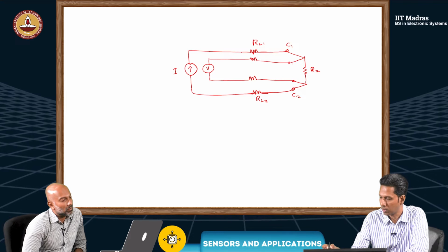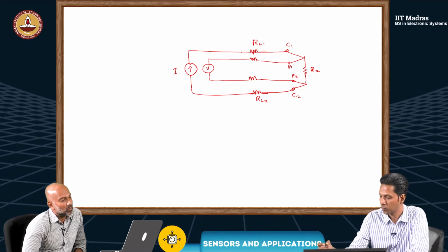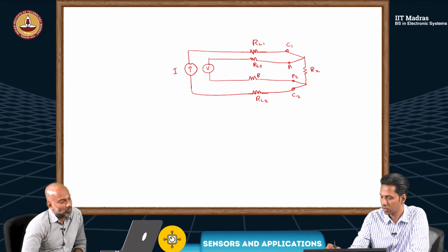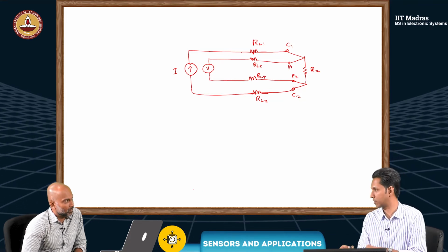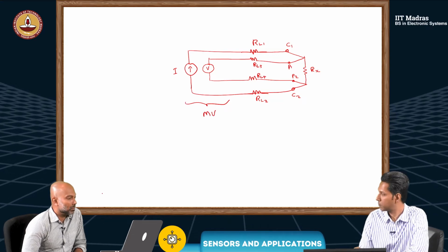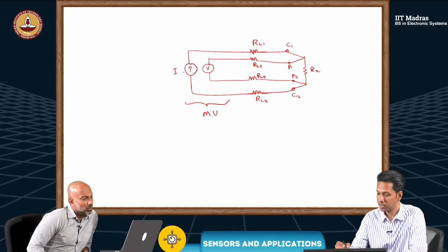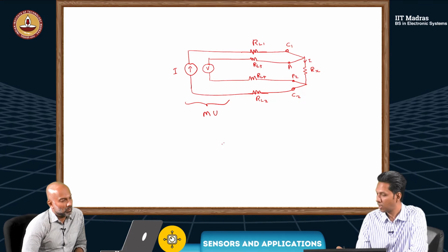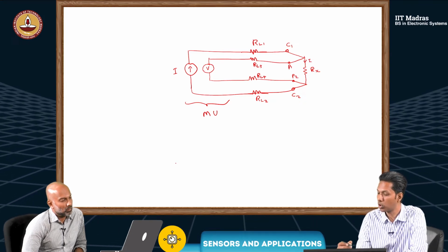And this terminal, let's say this is P1 and P2. And this has got RL3 and RL4. So these RLs represent the lead wire resistance. This region is my measurement node. So what we said is, let's say this current I is flowing through this, and then it has got I into Rx voltage there. I measure it using a voltmeter here.